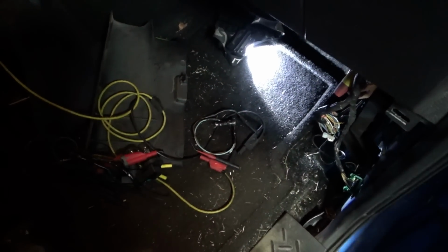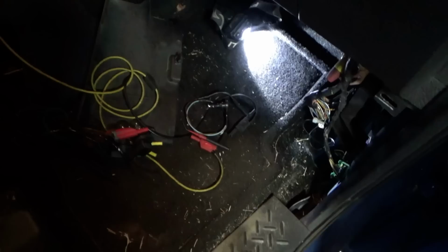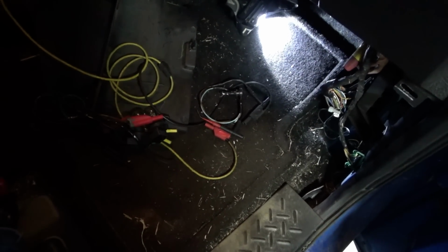Let's pop in a 5 amp test light instead of a 10 amp fuse just in case there's a short circuit there. Why is that fuse missing? I don't know. I guess it just walked out on its own. It just fell out. Yeah, let's make sure there's no short circuit on there. Turn the key on and wipers should work.